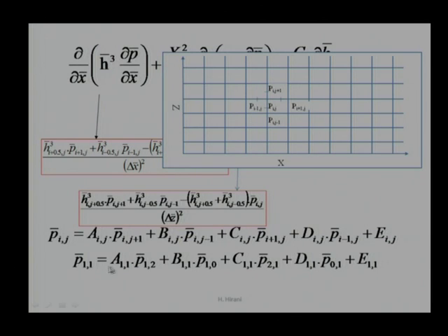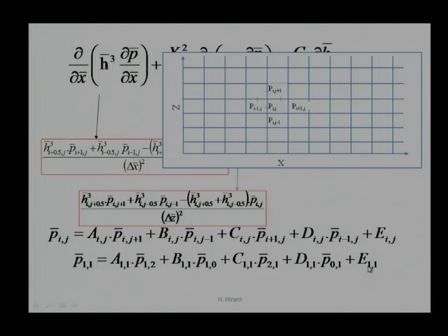And what we need to find out next: as this term is a11 and we are trying to find out a12, we are getting the value from a12 and a21, which are not known to us. We are expecting results from unknown things. That is why we require iteration. We need a sequence of iterations so that we can finally come to one convergence point. Initially, we can assume pressures are 0 everywhere, and only this term is going to give me results.